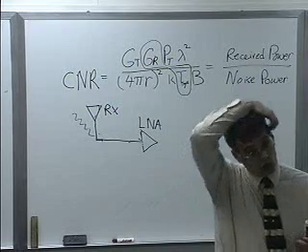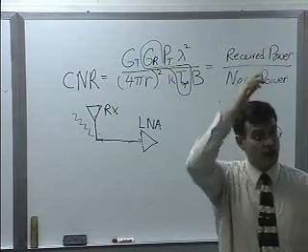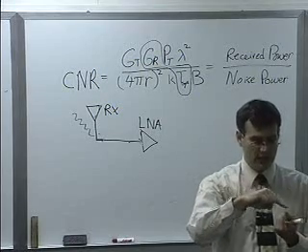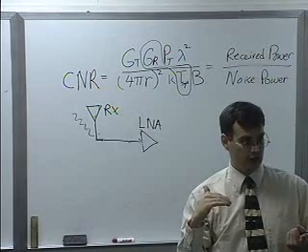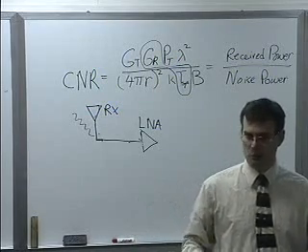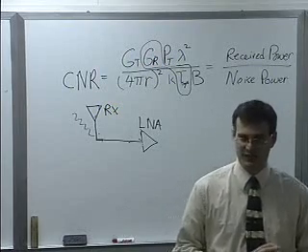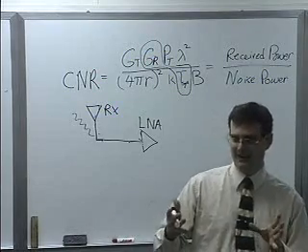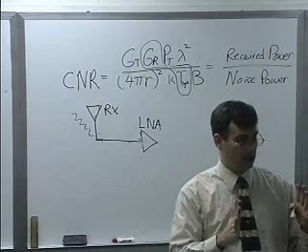So in other words, the question is, you can make it wide, right? You can make it wider, probably. The question that Alec is bringing up is that you generally make this filter tighter for terrestrial receivers because they operate closer to the ground, and there's more stuff and traffic around here, more potential for somebody to walk by with their wireless transmitter in their pocket at 1900 or 900, or there's more chance of getting a Wi-Fi transmitter close to it. And that's true. You would tend to want this to be tighter at the lower frequencies.